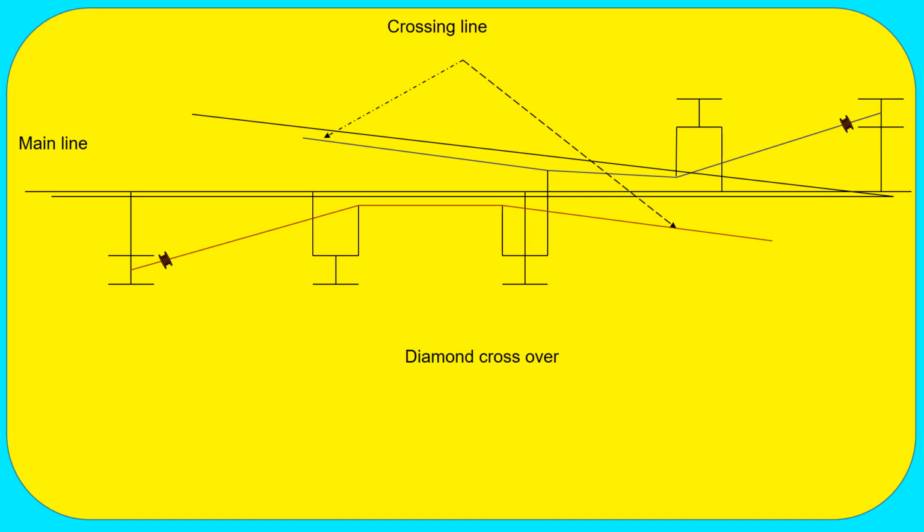Though we provided overlap type previously, in past days it was not this overlap type. Now where this cannot be avoided, we are providing overlap type. This is called diamond crossing. One running track is crossed by the other running track. It is not connecting, it is crossing, passing that track. Try to understand the difference. In our turnout and crossover, we are connecting the two lines, but here one track is crossed by the other running track. So it is crossing, diamond crossing.